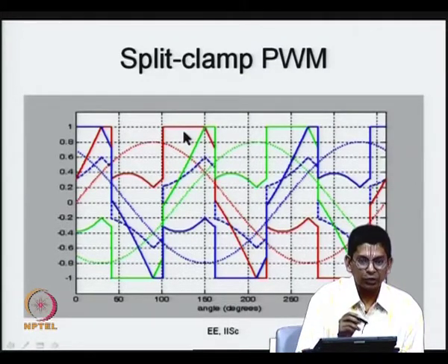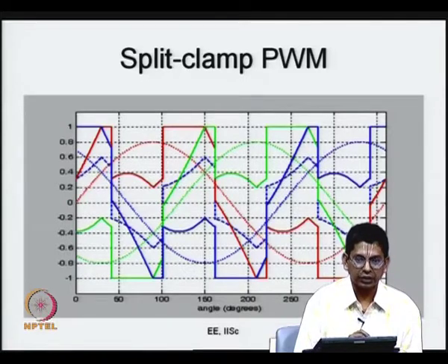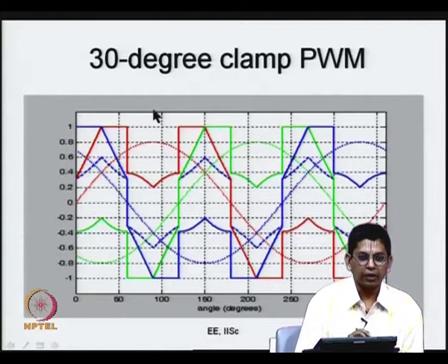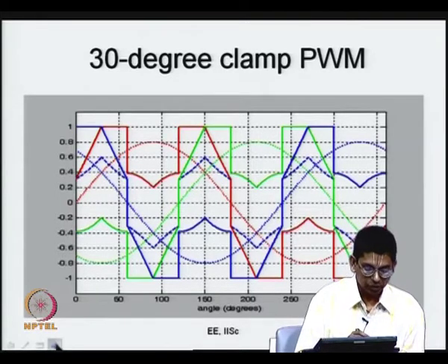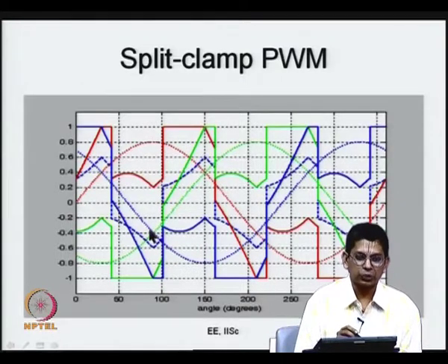It is a little difficult to see this possibility, but it exists and has not been thoroughly discussed. It is only in a very few recent papers that you find this possibility getting discussed, whereas the other possibility has been commonly seen now. This is also possible, and it is actually advantageous in certain lagging power factor situations from the point of view of switching loss, as we will come to later.